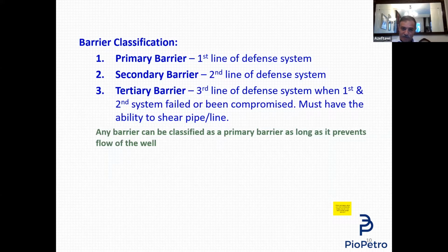Remember, before the job, you tested your Christmas tree and pressure control equipment to 5,000 psi. Now, after you perforate, the hole is full of mud. The surface pressure reads 5,020. Can you continue the job or not? I'll leave you a few seconds. Of course, I will not hear your answer, but I can imagine it.